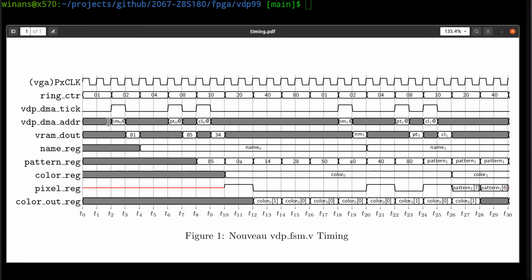And too long, in terms of pixel clocks, is on the order of 4 to 5 VGA pixel periods in a row. If we wanted to continuously read in DMA mode, we could for 4 or 5 time periods before we've done it so long that the CPU might not be able to access 2 in a row if it's running as fast as it can, okay?